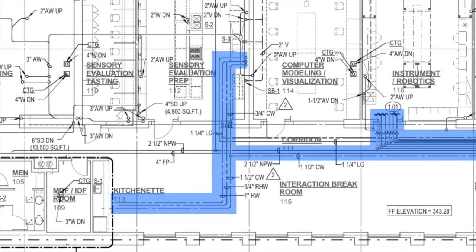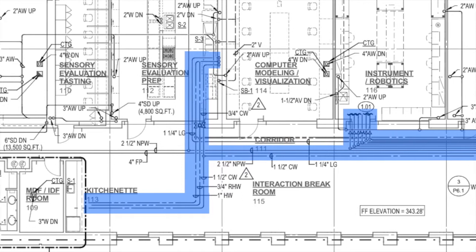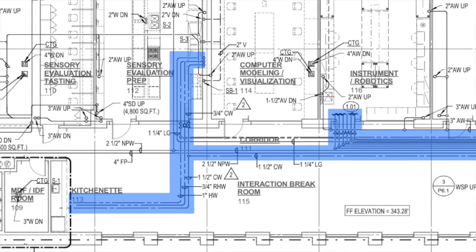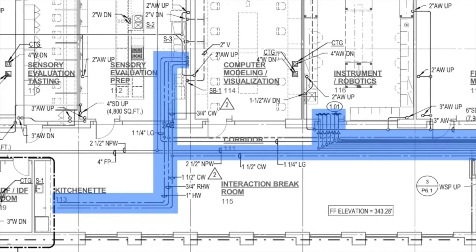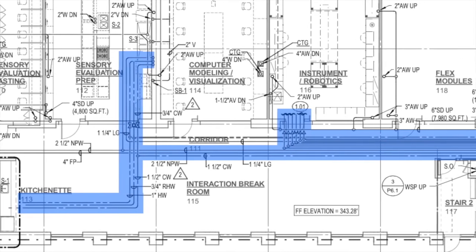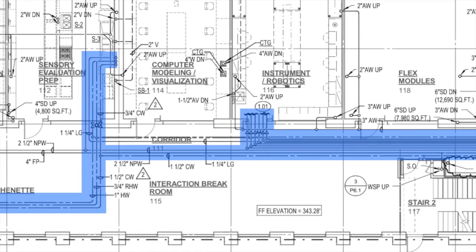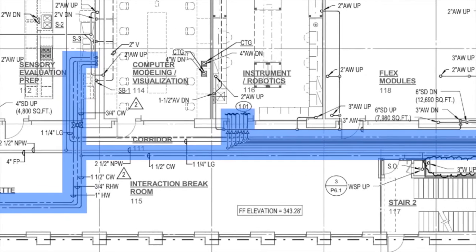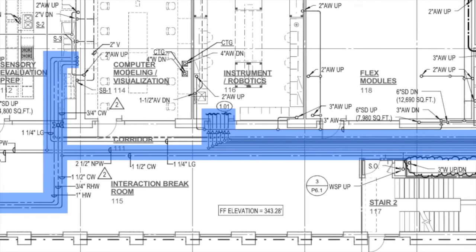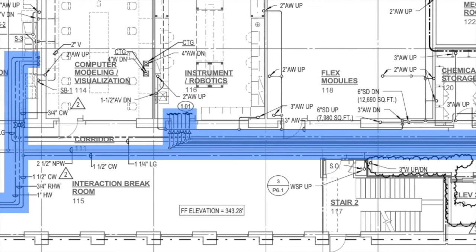After crews have poured the floor slab and the slab has cured, steel members will begin to be installed. This process will continue until all 3 floors have been framed in steel. Decking and stair access will also be completed before any further plumbing can be done. During this part of the process, it is important to ensure that holes are placed in the floor slab where future piping will be run up and down each floor. Once the floor slab has cured, plumbing can begin again.